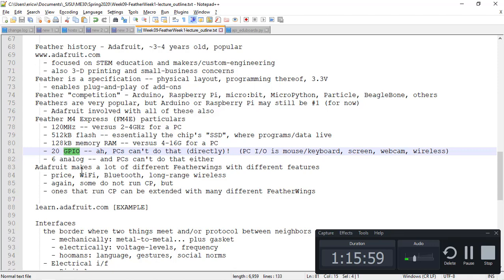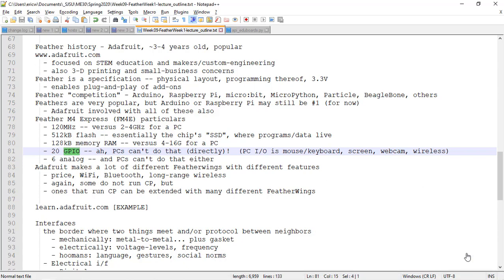So basically, in a software fashion, you can generate waveforms through an audio amplifier chip, which is a couple of bucks, to actually play sound that is composed by the microcontroller, not just playing back of something that's been recorded and stored on an SD card. And as I've already alluded to, there are a bunch of Feather Wings that have a lot of these pre-canned functions on them, of varying prices. So a lot of networking boards, display boards, sensor boards, all that.